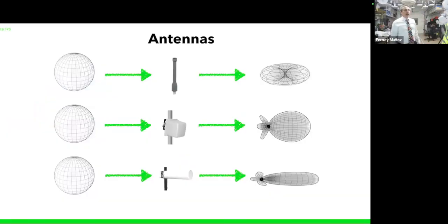There are three main types of antennas that we talk about. We talk about omnidirectional antennas. That's the one on top that is like a donut. And when it says omni, omni means all. Omni-powerful, omnipresent. Omni means all. Of course, it's not an omni-omni, because omni would be what? An isotropic radiator, that it sends energy in all directions. Omni is short for omnidirectional in the horizontal plane. Any antenna that is omni, it covers 360 degrees around it.